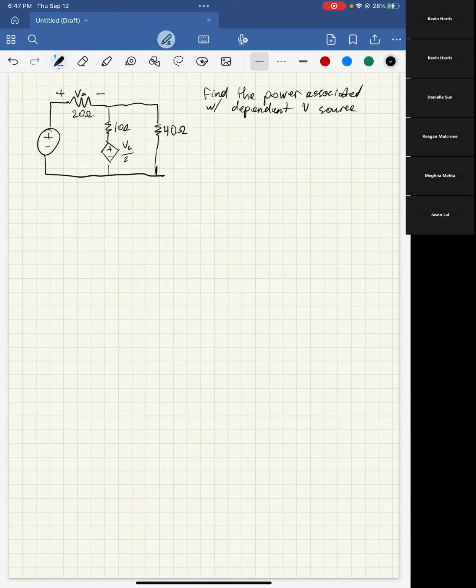To start, we want to define our ground, or our 0 volts, whatever you want to call it. It's basically always going to be the bottom, where you have a bunch of components connected. It works out and just makes everything make more sense. The only real node we have besides that 0 volts is up here. I think the terminology was an unimportant node, some word like that. I'll call that V1.